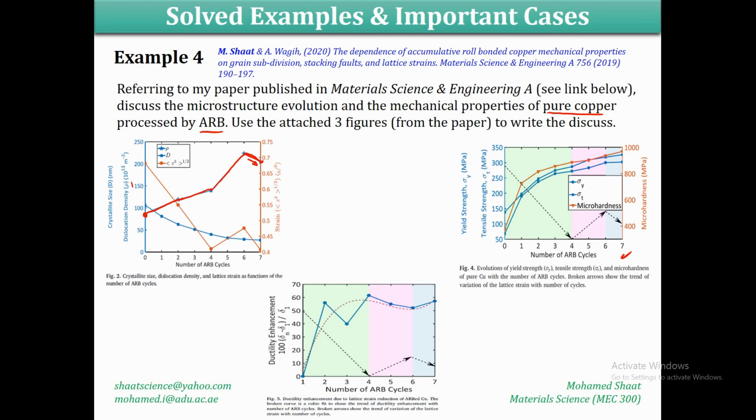One of the things is the grains. After the first cycle, it will be elongated. After the second cycle, it will be elongated further. After the third cycle, the grains will start to be broken down. We're going to start another phase of the grain structure, which is grain subdivision, where we end up with subgrains that will be formed inside the material microstructure.